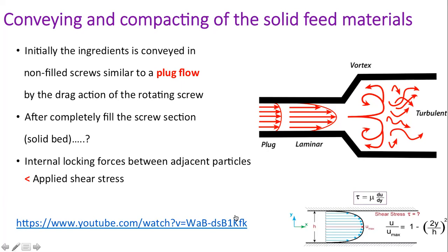Now the screw is moving continuously. Then what happened? The dragging action is there. Plug flow, you can remember. Now the solid bed is there, and it starts to melt. The raw materials are melting, mixing, all these things are happening now. Pressure also develops.